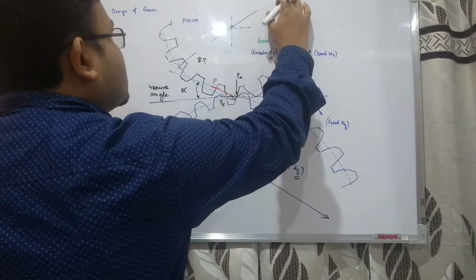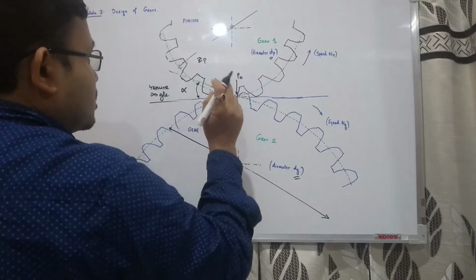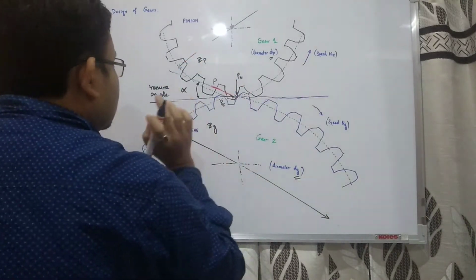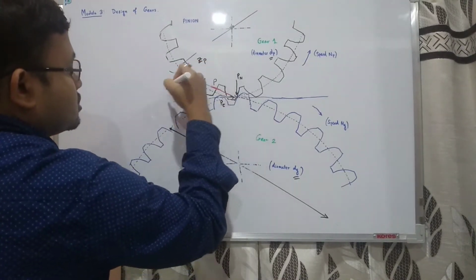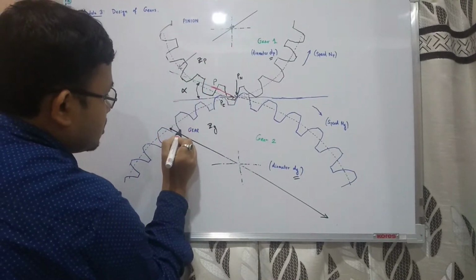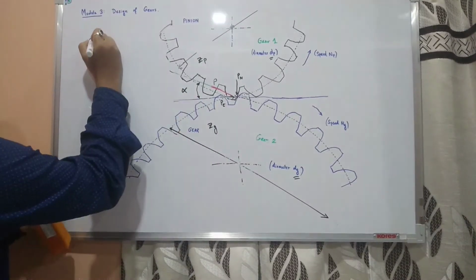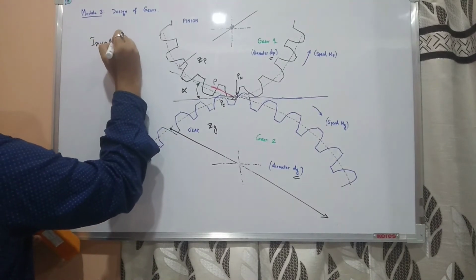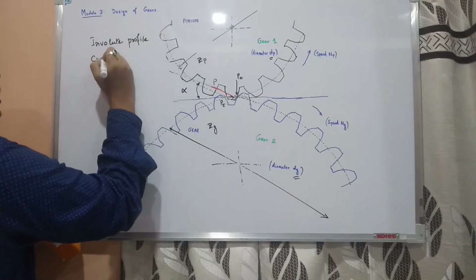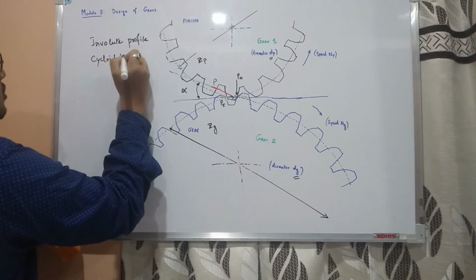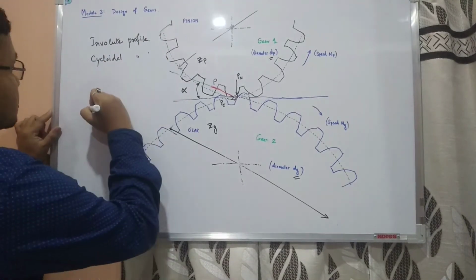Now look at this. Next, alright, so we have talked about this module and all. Now something which is very important. Let's talk about the surface of the gear tooth, I mean their surface profile. Basically we have two types of surface profile: involute profile and cycloidal profile. Profile means what I am actually talking about is this surface of the gear.